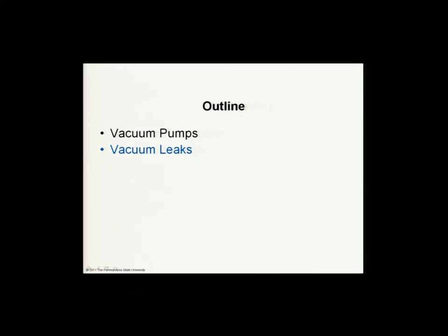So we've talked about vacuum pumps. I want to just mention a titanium sublimation pump one more time just to complete that subject. And again, just to remind you, that is another one of these dead-end pumps like a cryo pump. And as I said, it uses some kind of a titanium source which is volatilized, so you have some titanium vapor, and it pumps by molecules coming in.